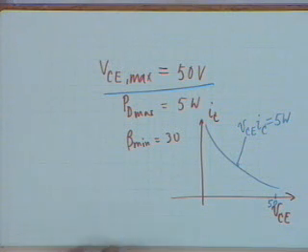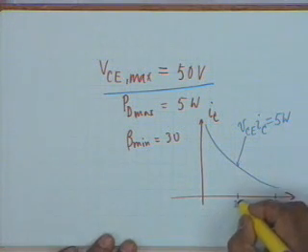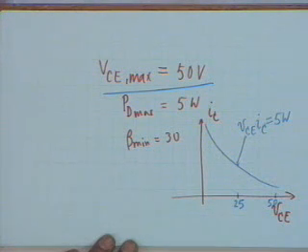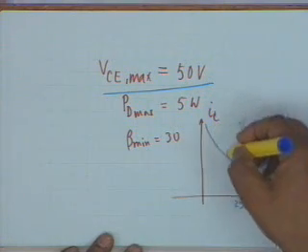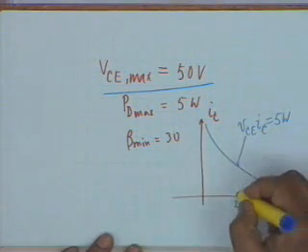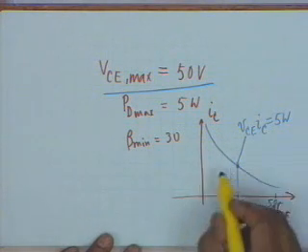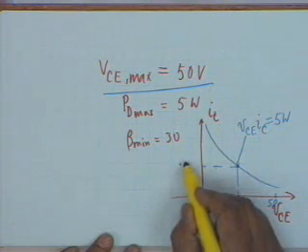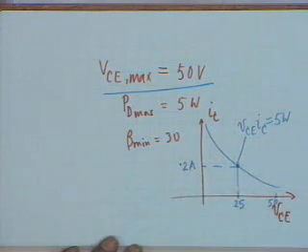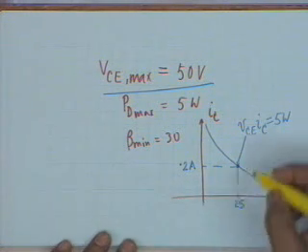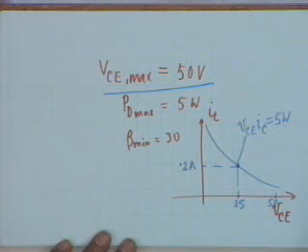Then obviously the maximum voltage swing can be 25 volts if the characteristics are ideal. So you mark the 25 volt point, and you know that for maximum power output your Q point must be on the PD max hyperbola, and therefore you go up and see where it meets. Obviously the current here shall be 0.2 amperes, and therefore your Q point is now determined, 25 volt and 0.2 amperes. Not only the Q point but the AC load is also determined.